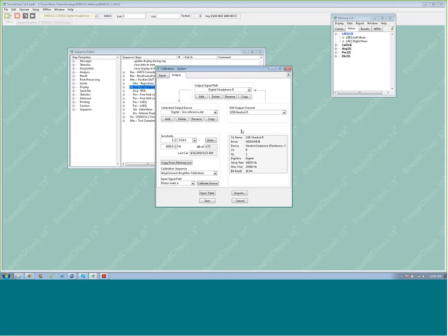For calibration, the only thing we need to do here is make sure that the digital level is assigned to full scale. And also, we need to set the sensitivity. It'll be set to 3 dB to get the offset to be the sine wave reference. Remember I mentioned that earlier, that the reference for the full scale for this particular standard is in reference to the RMS level of a sine wave rather than a square wave. So to change that, we'll change the sensitivity here to 3.